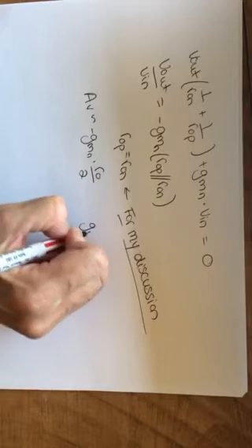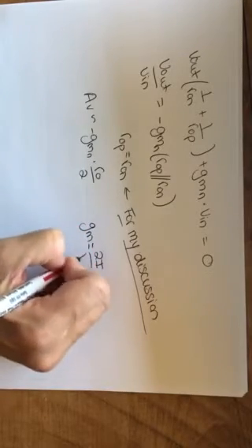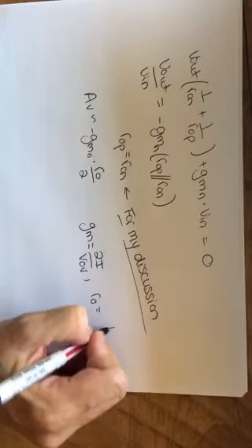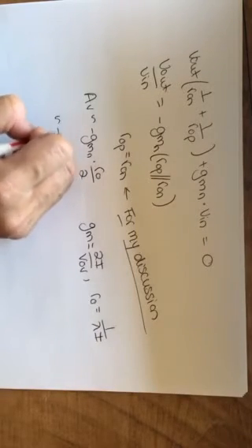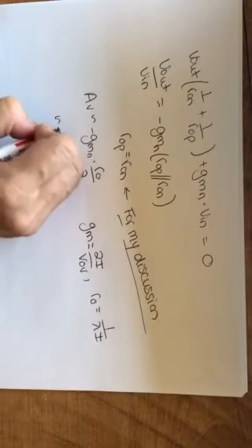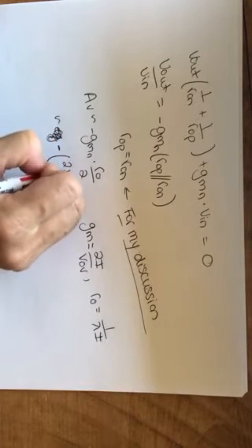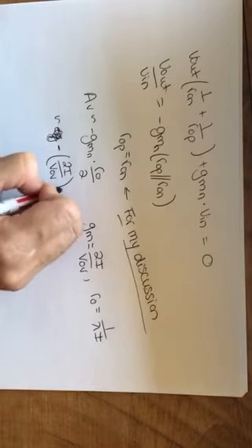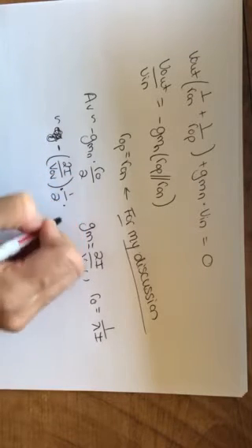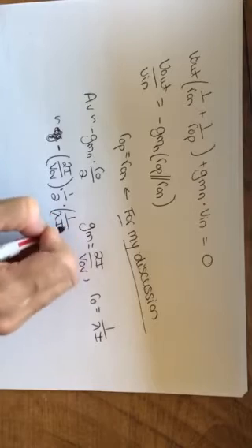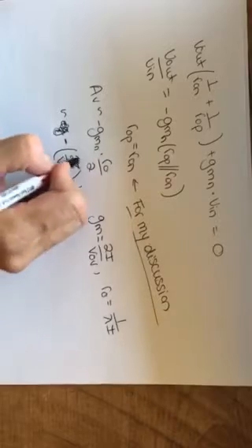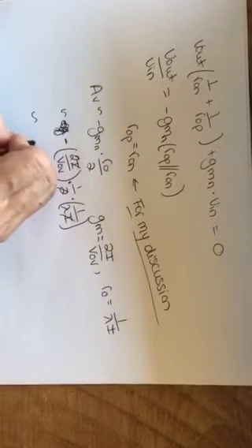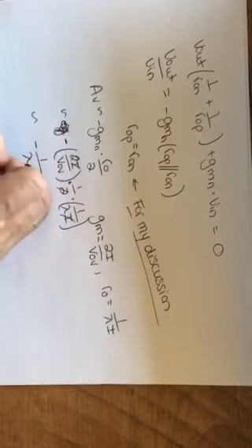And if I look at what gm and r0 are equal to, well, gm is 2I over VOV, right? And we know that r0 is 1 over lambda I. Okay, so let's plug those in. We're going to have minus gm, minus 2I over VOV times the 1/2, fine, times 1 over lambda I. If you look at this equation, the currents cancel, the 2's will cancel for this case, and I would have minus 1 over lambda VOV.